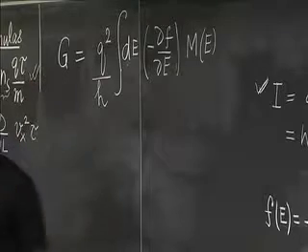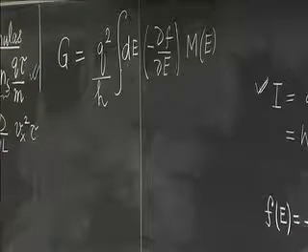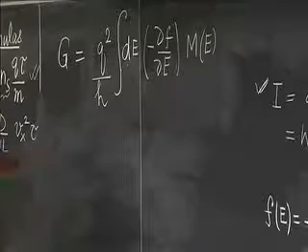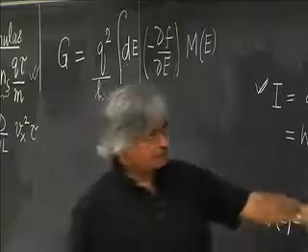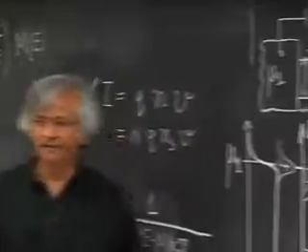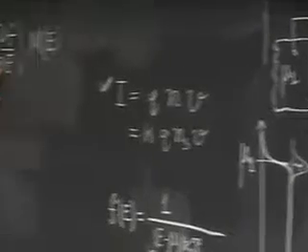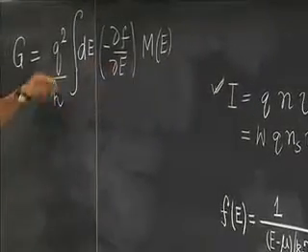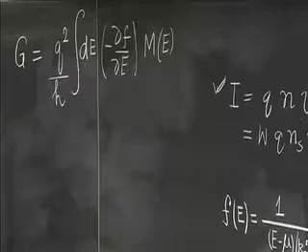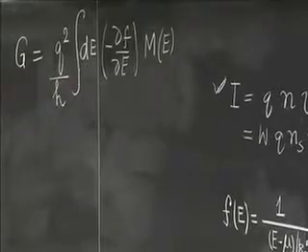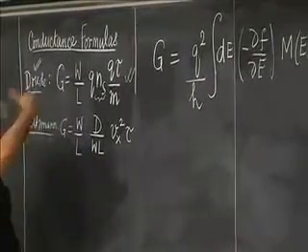And this is supposed to apply only to ballistic conductors. And so usually people say that, if the conductor is ballistic, that is, electrons get from left to right without any scattering, then we'll use a formula like this. But then it's not clear how to go between this ballistic limit and this diffusive limit. This is the one that's supposed to apply in the diffusive limit.